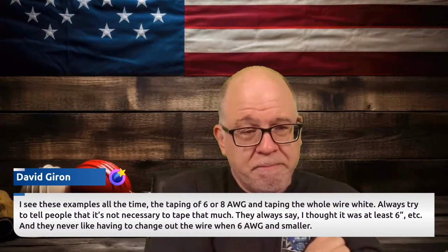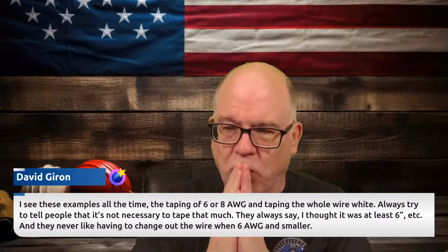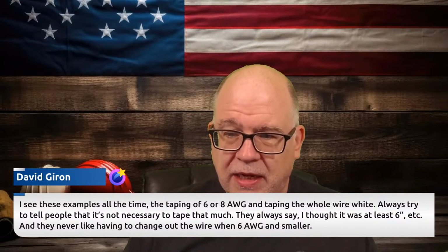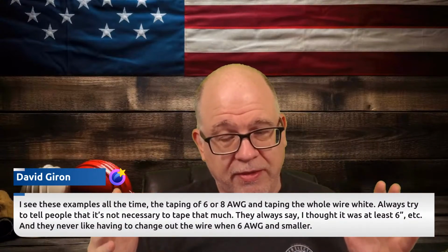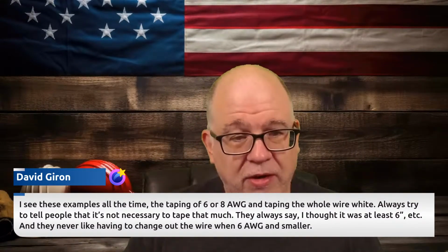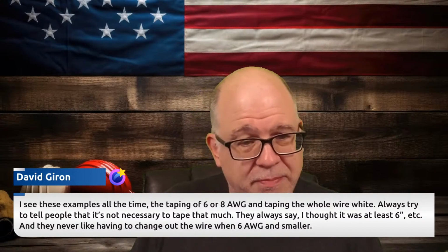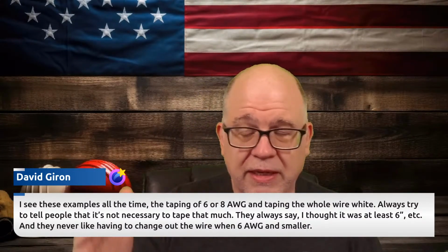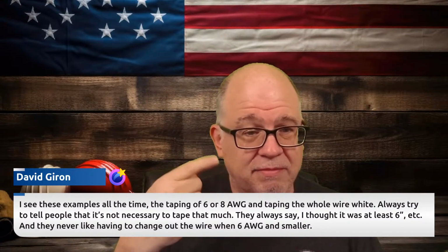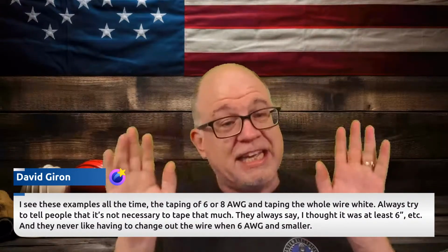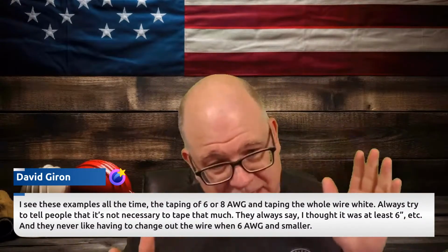Yeah, so that's a good one, because at the end of the day, when we're doing the identification, there isn't a size requirement for the ungrounded, the hots, okay, in that scenario. You can get it all black and put colored tape on it, whatever you want. There is no size requirement. You really only have to identify it at the termination. To be honest, in any case, you don't have to wrap the whole thing in red or black or blue. There's nothing that says it has to be at least 6 inches or whatnot.